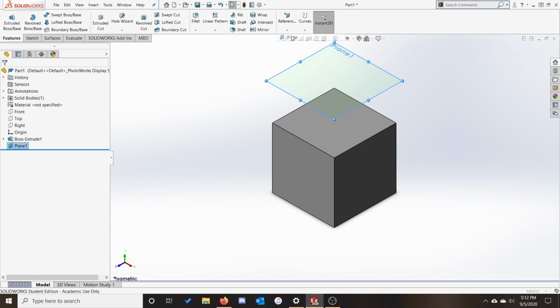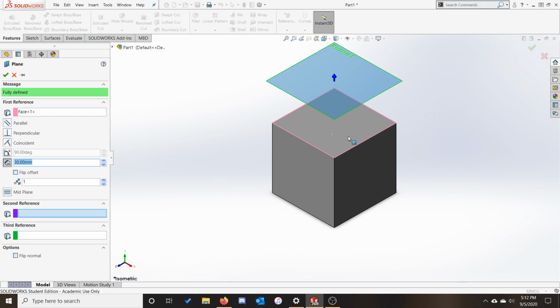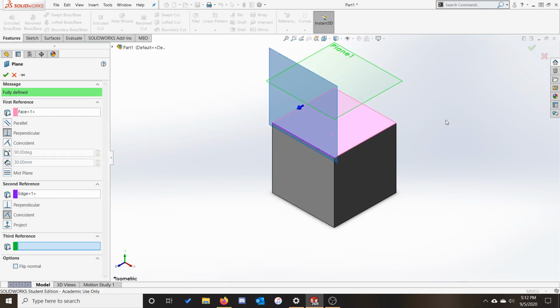First, we're going to need to open up our reference plane again. First, we have to give it a 0 plane, or the plane that our angle would be measured from. Next up, we have to give it an axis that will be rotated about. Here we can choose a sketch edge, a reference axis, or just about any straight edge that we could select. Finally, we need to tell it the angle that we want.